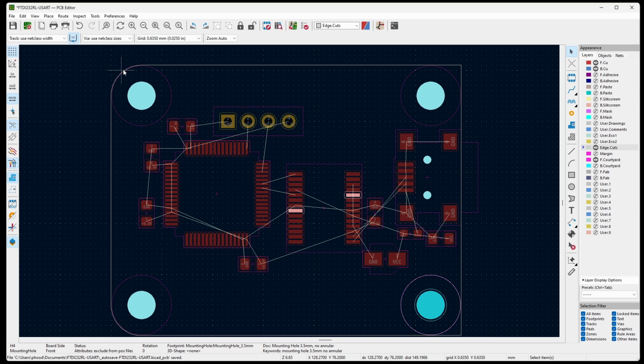Now, there is a way to just use these existing arcs and just copy them and paste them here. I think creating the arc is actually a little bit easier, but I'll show you how to do that. I'm just going to do a Control C and then Control V. I'm going to move it here and then just press R until it becomes located in the correct place. I do the same thing, Control V, and then R when I get it to the center of that hole. Done. Now I'm going to just do the same thing. Just move these ends to the endpoints of the arc.